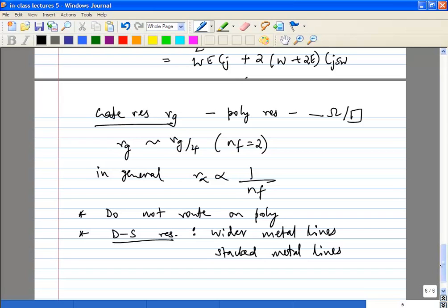It may not be the thing which is really limiting your performance, and typically for most mixed signal designs you may not worry too much about this capacitor. But there are certain cases, definitely RF cases, where you would worry about this capacitor, and some important cases where you have to be careful. If you're building a high speed ADC or something, you really have to be careful about these things.